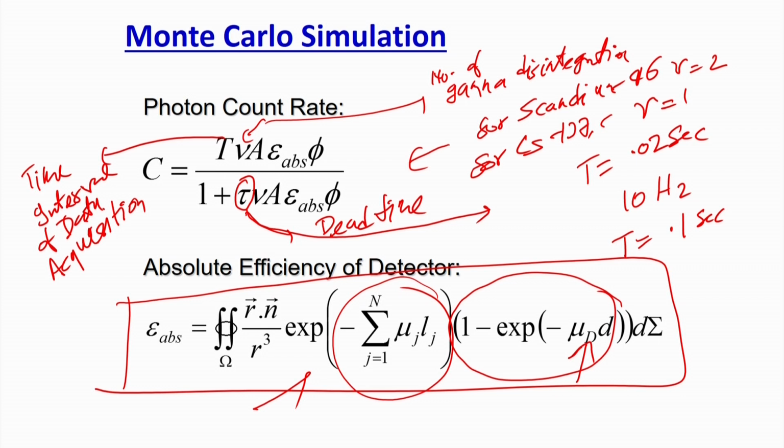Now, until you have the tau value and the mu d value, the in situ condition attenuation coefficient, you cannot go ahead, because you cannot calculate the counts. So, for that we do experiments for certain locations, say 150 or 200 locations, depending upon the column geometry. And then we tune our Monte Carlo program. Why Monte Carlo? Because we are randomly throwing the photons to find the solid angle and whether they will be attenuated or not within the bed, and where they are coming in and going out.